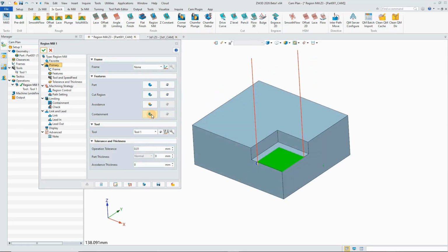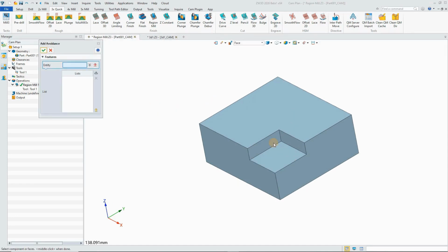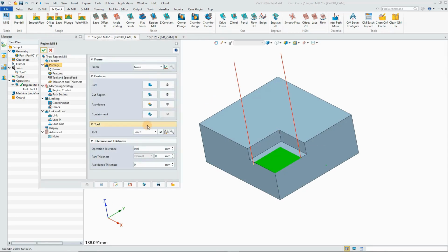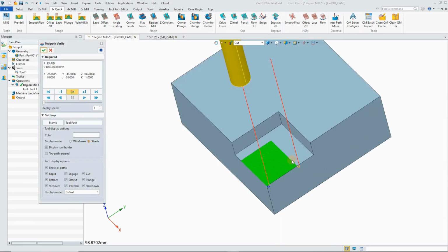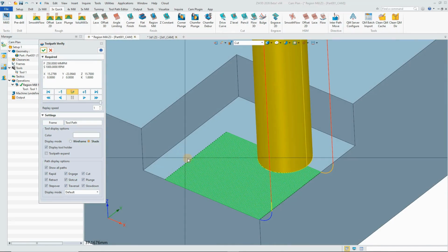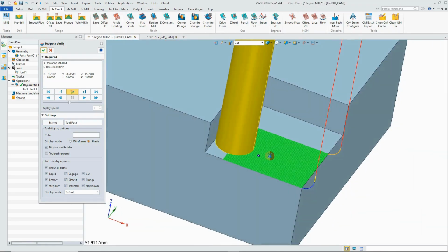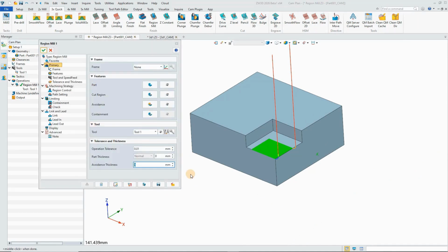When a certain part or surface needs to be avoided or there is a separate requirement for the avoidance distance, it can be set to avoidance, that is, set the inspection part, and set the avoidance distance at avoidance thickness. The avoidance distance of all inspection parts in the same process is consistent and cannot be set separately.